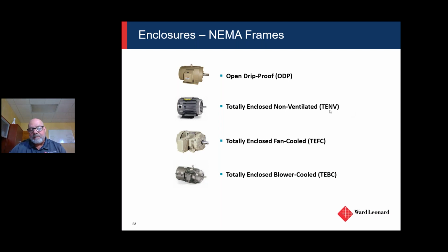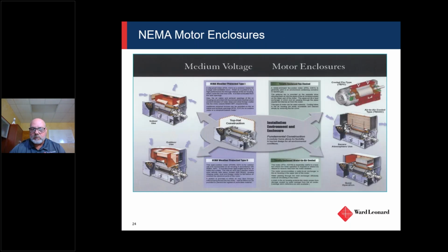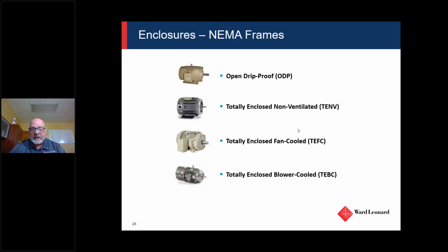Totally enclosed, non-ventilated. This would be an application if you had an air over motor. So if you were putting this on a belt driven fan where it's going to draft air over it, then that would be a good application for TENV. TEFC, which is really common, has a totally enclosed design with an external cooling fan inside of a shroud.